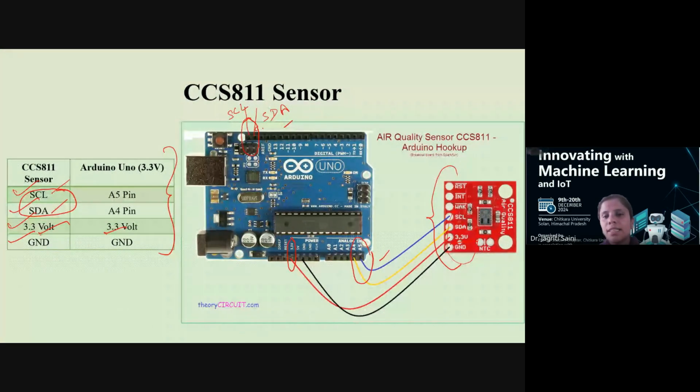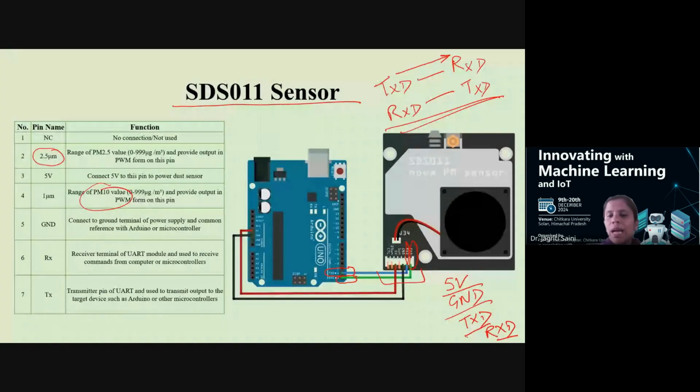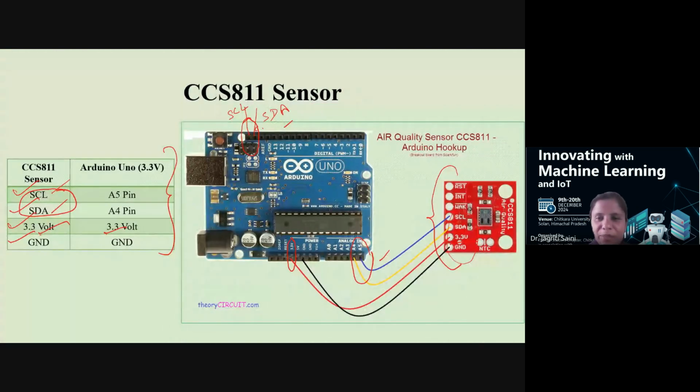Anyone in the chat box? Great. So I got one response, I2C interface, definitely. Other than this, we have discussed 2 more interfaces. So if I go back and we talk about this interface, does anyone remember what interface this one is, with TXD and RXD lines? Yes, a UART based interface where we have the communication through TXD and RXD. Very good. So at least we are able to connect with whatever we have learned yesterday, and proceeding from that we are making the connections over here.